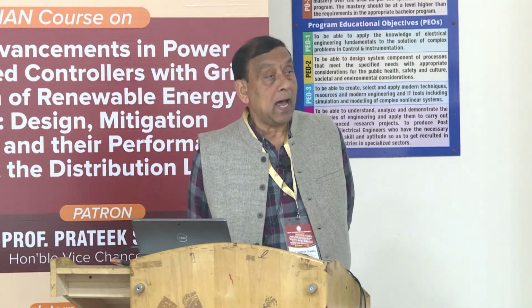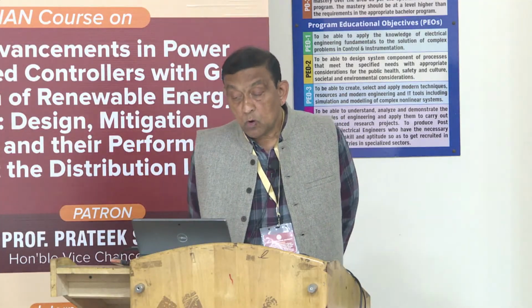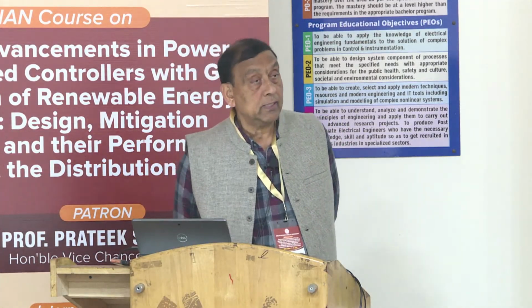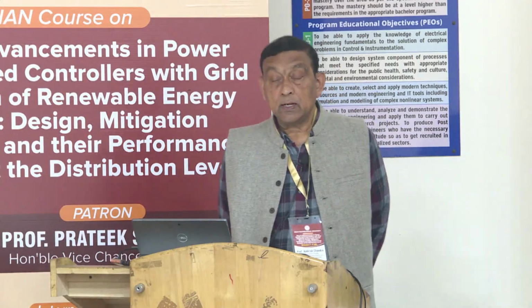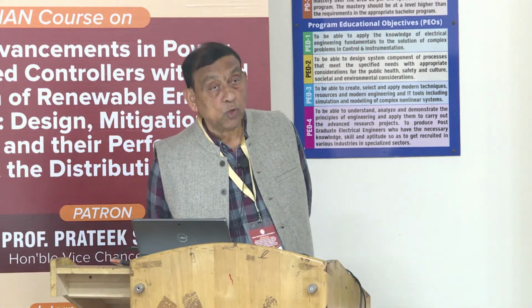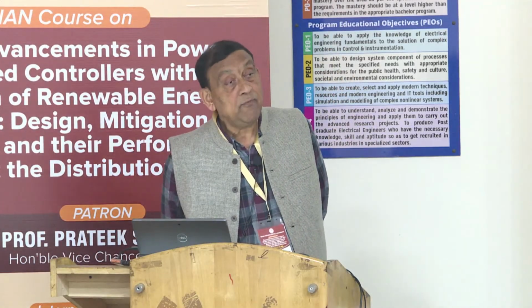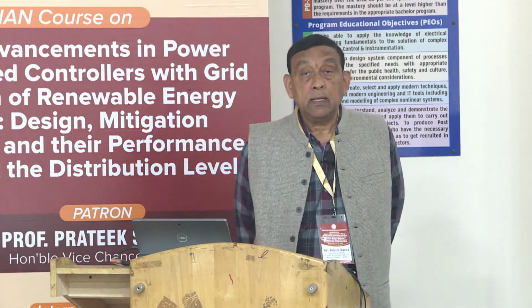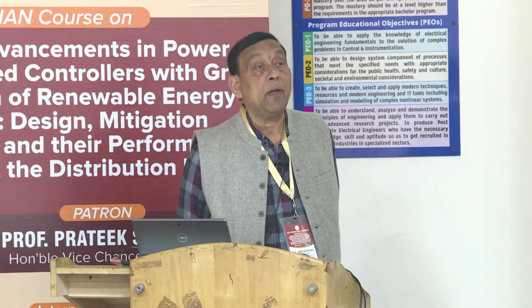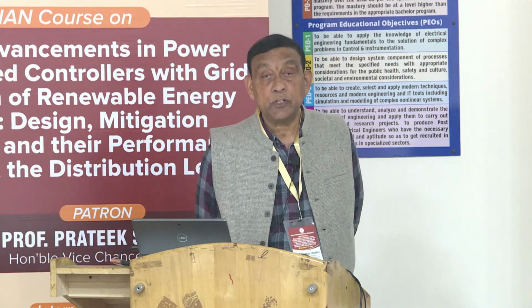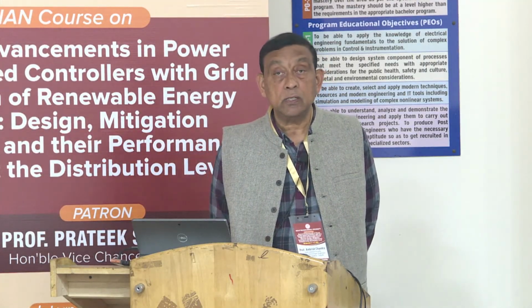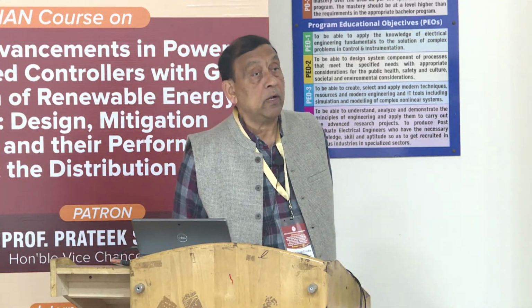And then we were talking about what problems harmonics cause, okay: increase in losses in conductors, and the reason we saw, like skin effect, ohmic losses, and then we were talking about the ferromagnetic losses like hysteresis losses and eddy current losses. So these are very important issues.